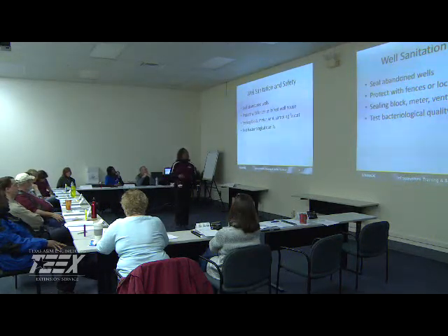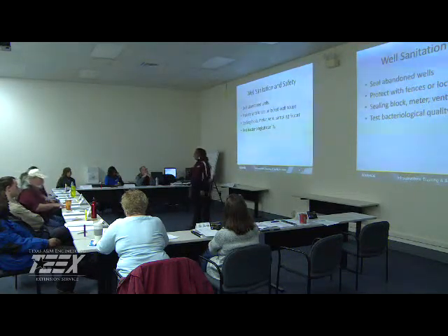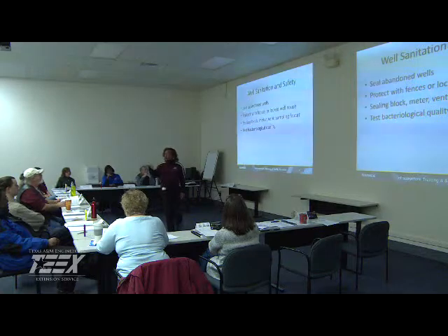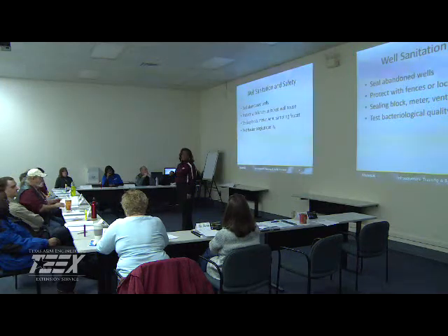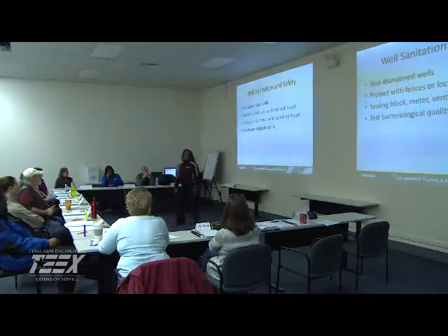And then, of course, we'll be testing for bacteriological quality. Before you can put that well into service, you have to have at least 3 days of bacteriological tests, and they have to come back with no coliform found. That's great. I like that idea. You all don't do that? 3 successive days.